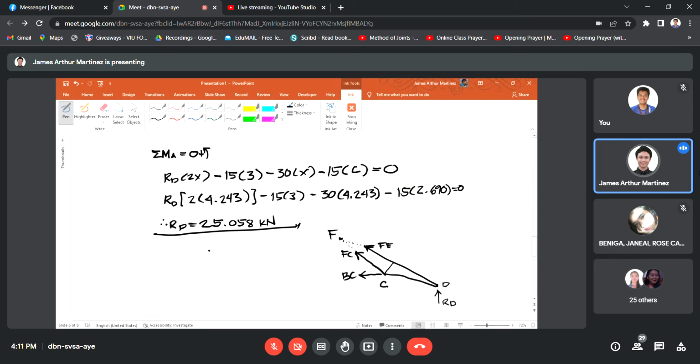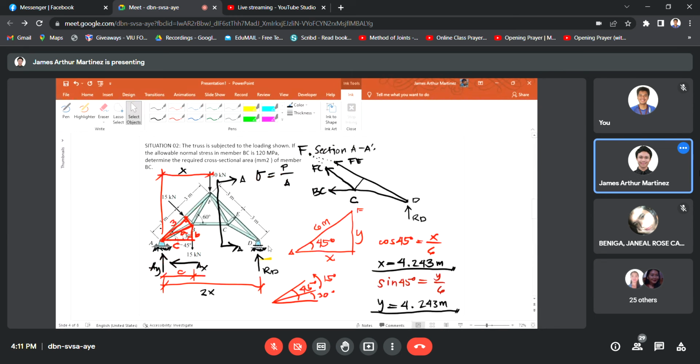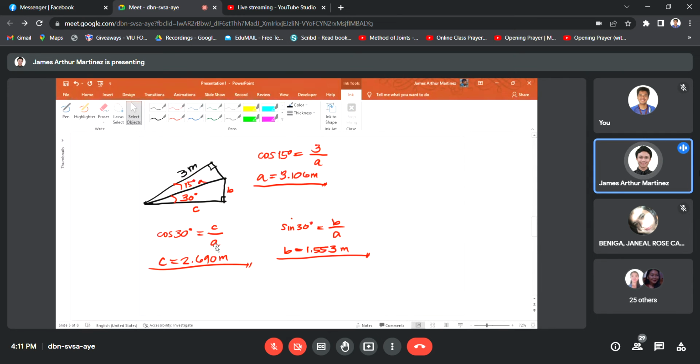Okay? Sige. So, summation of moment at point F equal to 0, having counterclockwise as positive. So, you have RD. So, RD with respect to point F will have a counterclockwise rotation, no? So, positive sign convention na ito ang consideration ng RD times moment arm. So, di ba this is point F and na-plus of the point F is just actually x distance, no? From point A and point B. So, that is just distance x.